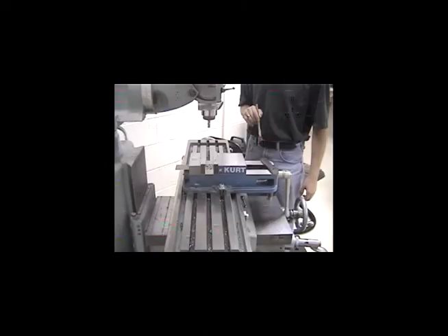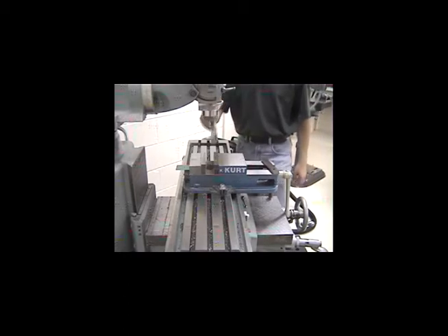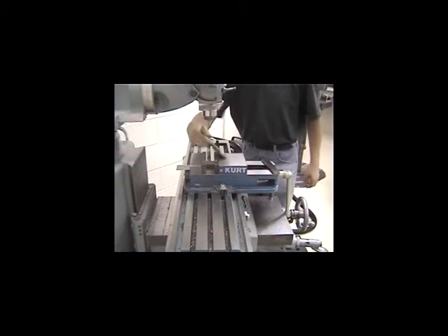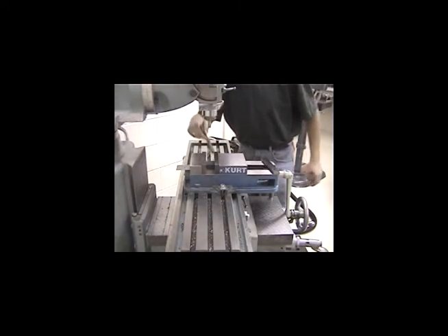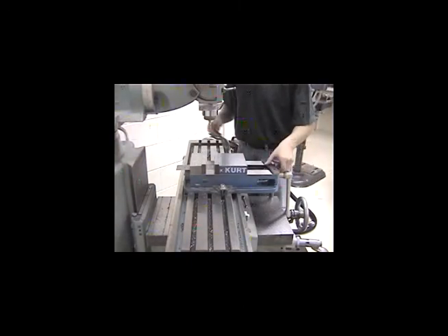Small parts should be placed in the vise for milling operations. The first step in placing a part in the vise is to clean out any debris or metal shavings from the vise with a soft brush. Unnoticed metal shavings beneath spacers or parts have ruined the tolerance on many a project.